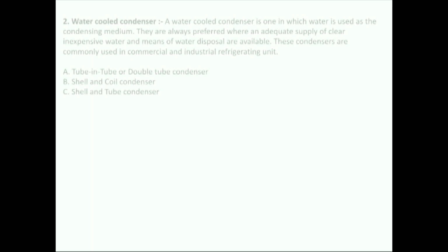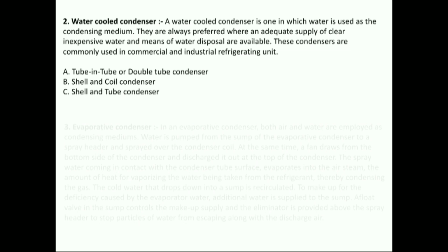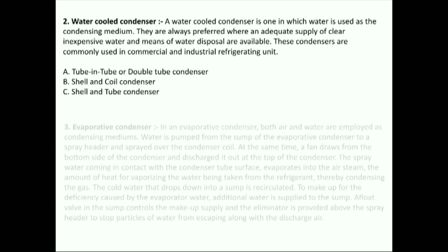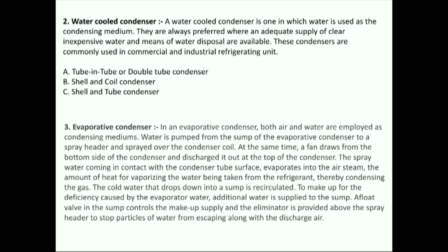2. Water-cooled condenser. A water-cooled condenser is one in which water is used as the condensing medium. They are always preferred where an adequate supply of clear inexpensive water and means of water disposal are available. These condensers are commonly used in commercial and industrial refrigerating units. A. Tube-in-tube or double-tube condenser. B. Shell and coil condenser. C. Shell and tube condenser.